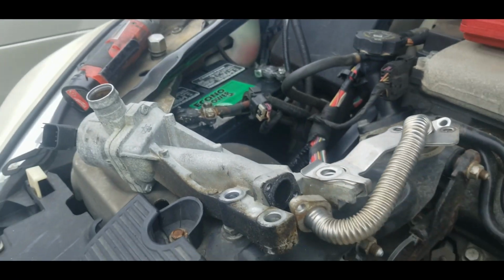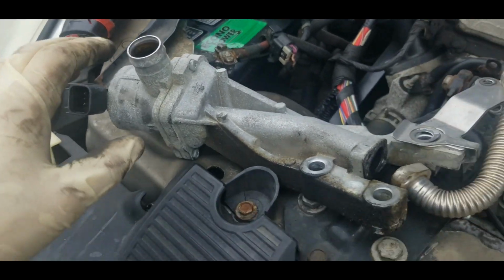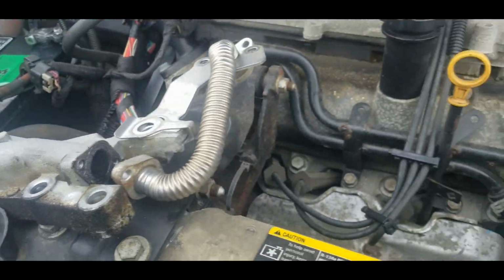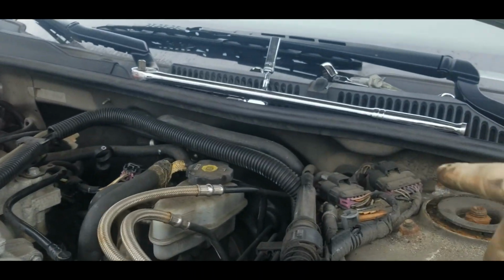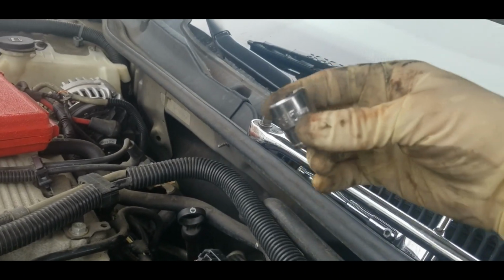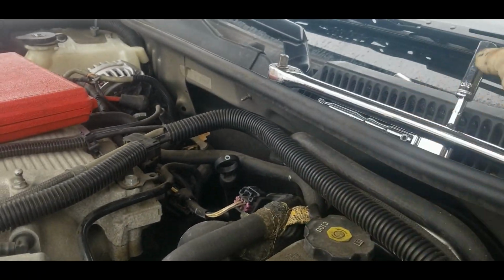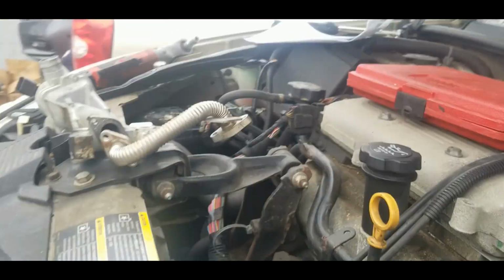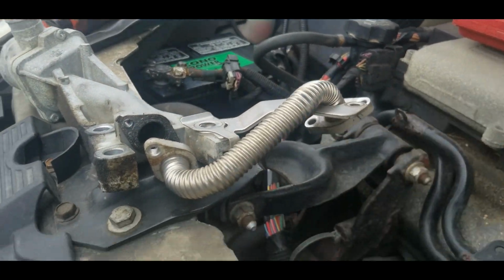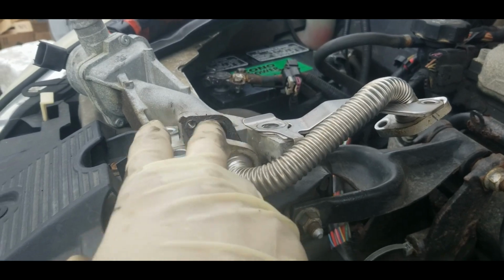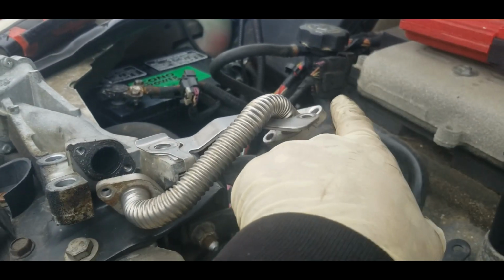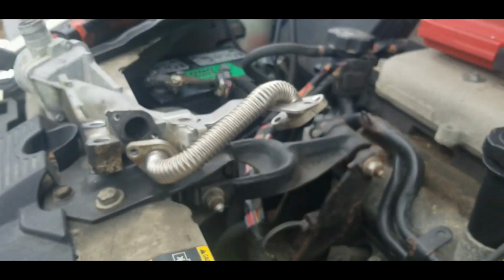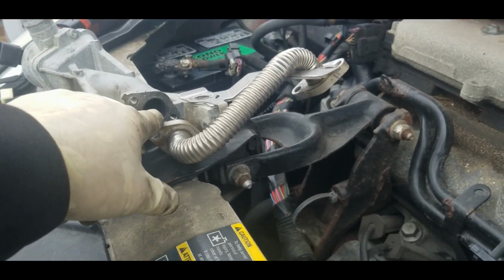So this is that big piece that I was telling you about. That's the check valve. So these are the 3 15mm bolts I got off. I mainly used my breaker bar with a regular 15mm socket, and I used this 10mm socket to unbolt this little pipe right up here. There were 2 10mm bolts up here. But pretty much what I did, I took these 2 10mm, I took these 3 15mm, and I took the whole assembly out, and then unbolted up here.